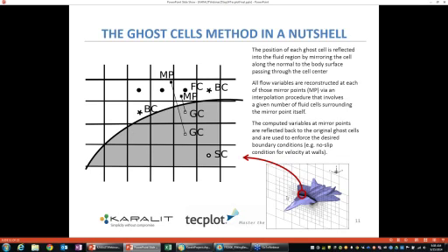So if we zoom in, for example, on a section of that complex geometry intersecting the grid, in immersed boundary the grid is categorized into broadly three parts. One is the fluid part. The other is cells being intersected by the geometry, called boundary cells. And then there are additionally ghost cells, which don't appear in traditional CFD, but in immersed boundary CFD they do. They are part of the solution, a layer or two of them.